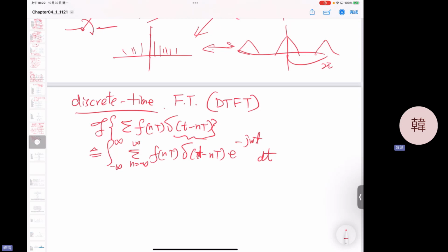But now your signal becomes sampled. How do you sample? You multiply by the impulse train. Every T seconds you sample 1 point. Every sampling time you take one signal there. So it's just like the triangle shape multiplied by the impulse train.